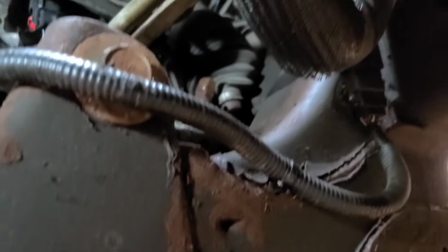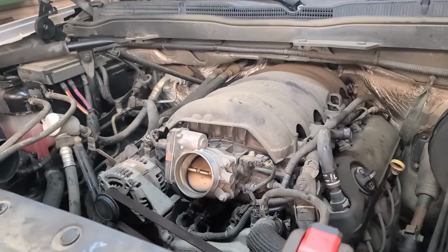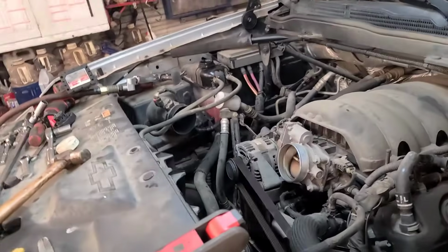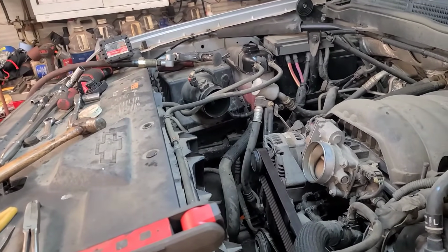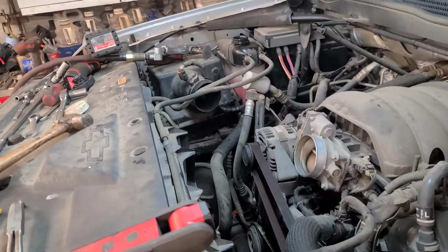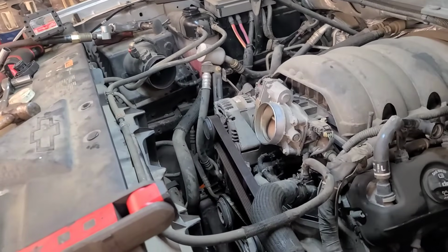Well, I got to put that steering gear shaft coupler back together again. Should have cleaned the rust off that while I had the steering gear out. So it's mainly back together again. Alternator's back on, battery's hooked up, coolant's full, engine oil's full. I have to check it after I run it, but I'm going to prime it.